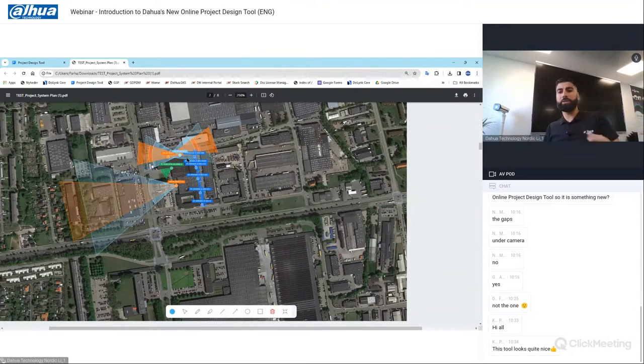But more important is to make sure to have good preparation, good planning, and understand why you're choosing these specific cameras. Consider sometimes cameras with more narrow angles when we are talking about perimeter protection, because there's no purpose in watching roads, bushes, trees, walls, etc. We could sometimes choose better cameras with better coverage instead of having more and more cameras, which will increase the labor cost. So that was more or less it.